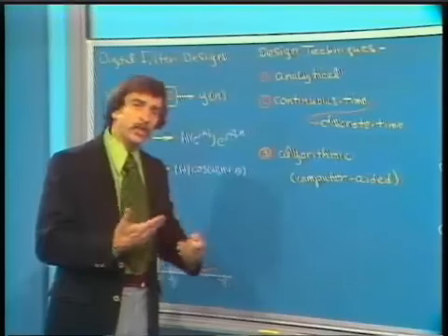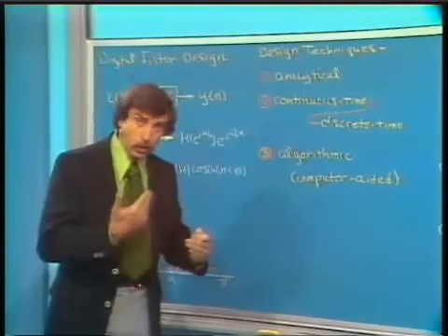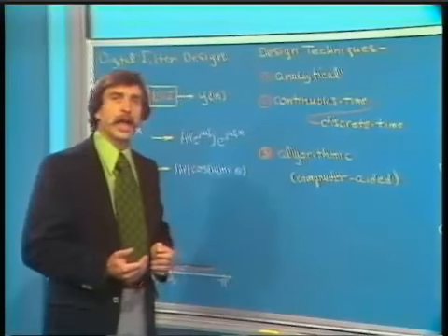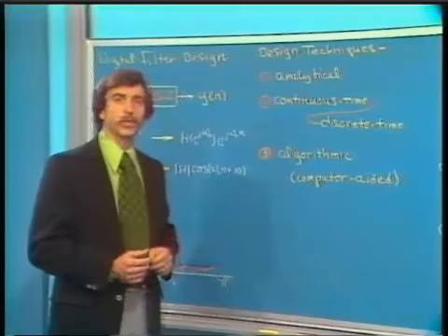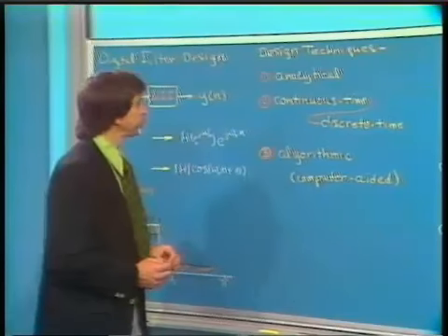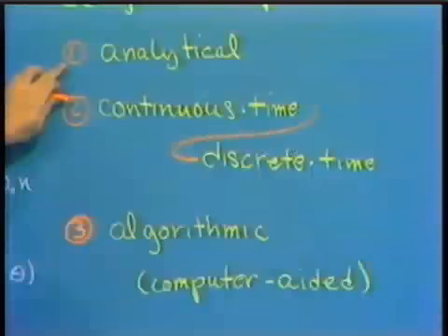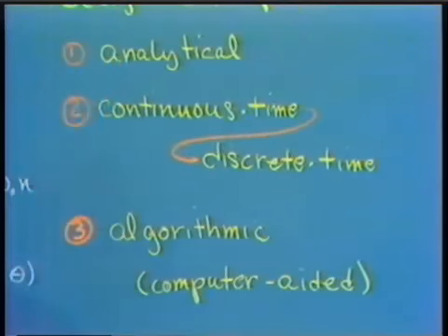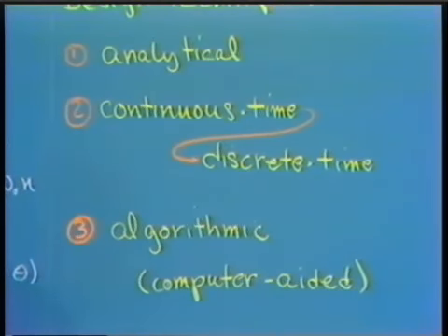The approximation is carried out through an analytical procedure and results in a closed-form transfer function. That, in fact, is a very common class of techniques for continuous time or analog filter design.